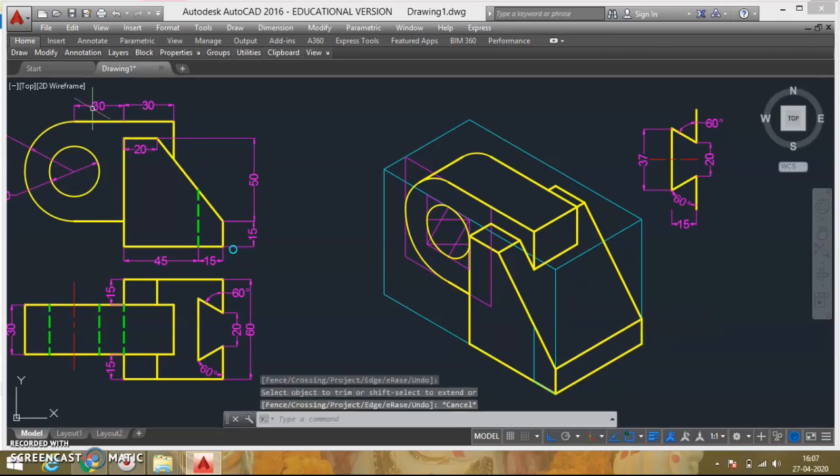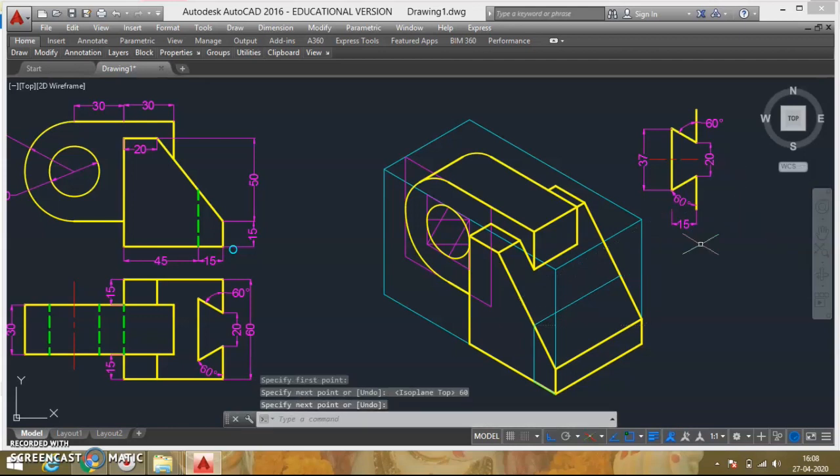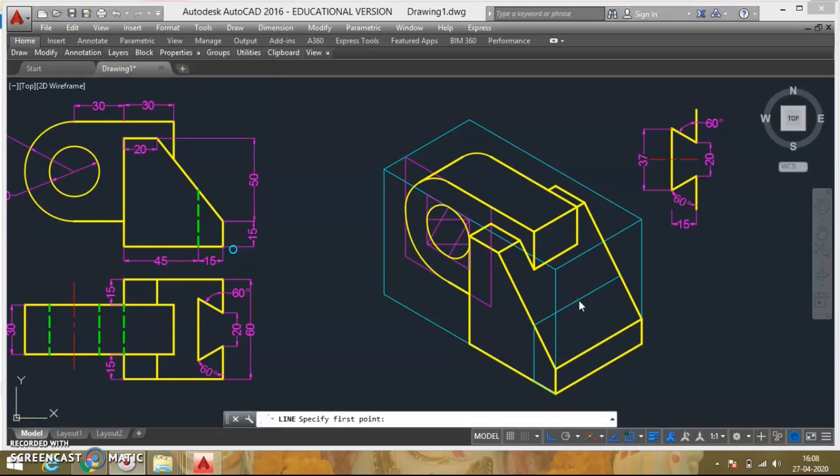Once you get the intersection, you can draw a line there which will be parallel to one of the isoplanes. So that line will be like this for a distance of 60 mm. Now once you get that line, I can measure those dimensions on this line and draw that slot. To do so, from the midpoint I'll measure on this side 18.5, and again from the midpoint on this side 18.5.